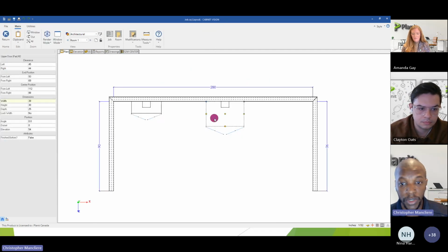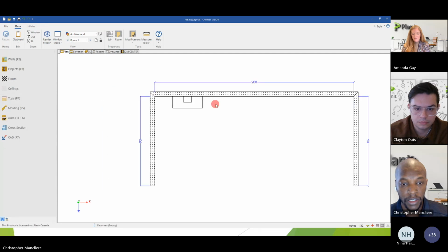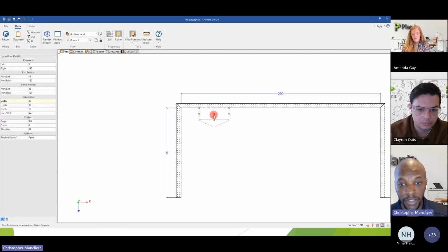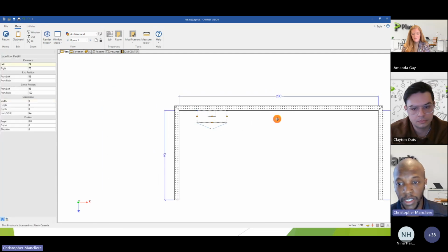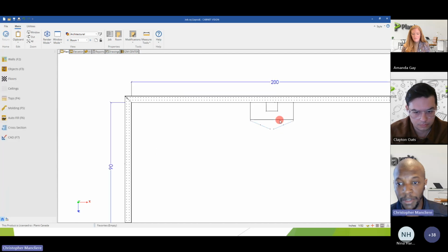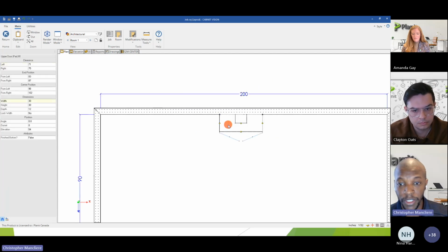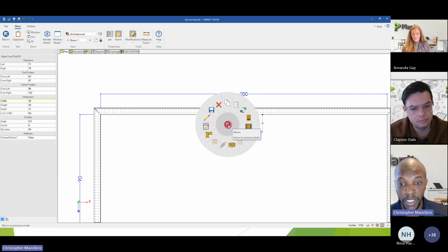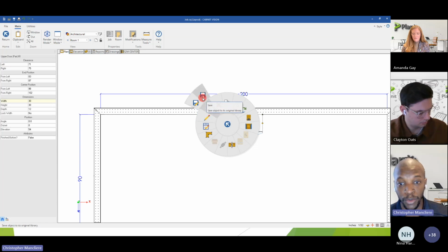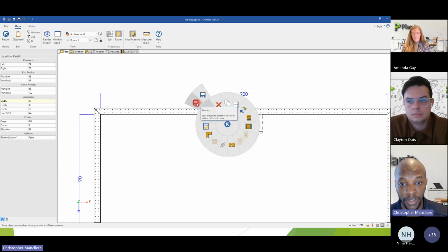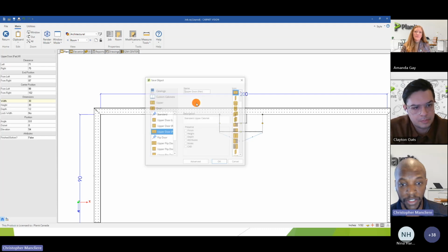So if you have your cabinet shaped and you want to save it, this is very easy. So I can get my original cabinet again. You simply right-click on the assembly, and you will want to select the option to save as. Save as is to create a new copy of this cabinet. Unless you want to override it, you can click save. But let's say we want to create a new assembly in the catalog.